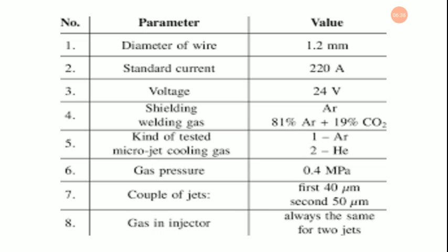The shielding gas is 99.99% argon and the flow rate of the shielding gas is controlled by a valve meter. The base metal is AA7075 T6 aluminum alloy plates. A single pass welding process is performed because the thickness of AA7075 T6 aluminum alloy plates is 3.46 millimeter.